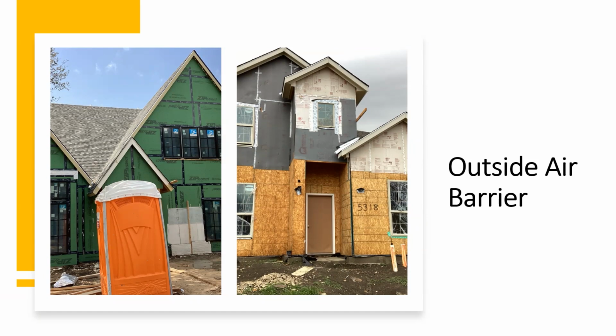We've got ZIP on the left, which is really good. It's actually consistent and it actually butts together. You have a proper tape that needs to be done. You have to follow a certain protocol to tape those seams. But when you have multiple different styles of materials, we got T-ply, we got white board, we got the gray board, we got OSB. Sometimes we'll have an R3 board. They all have different thicknesses. But whatever means are necessary need to be taken to air seal these correctly.